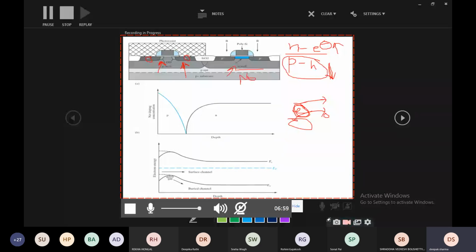So there is no LDD here on the right hand side. And one more thing we are seeing here, the photoresist, right? Wherever there is doping, this thing we have already seen in previous classes, right? Whenever there is doping, one transistor will be protected. Say this ion implantation of boron, if it is not required on the other side, then it has to be protected, and it is protected by photoresist that they are trying to explain here, right?